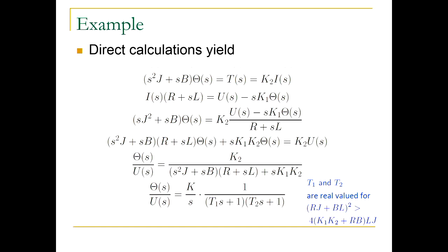When the Laplace transform of U is 1 over S, that's a step signal. When the Laplace transform is 1, that's an impulse. So we were asked in the first instance to apply an impulse. Basically, this is 1. And we were asked to observe how the shaft angle changes, right? So that means that when U is 1, then theta is equal to all of this. Now, can I find this thing directly in Laplace transform tables? Probably not. So what do we need to do?